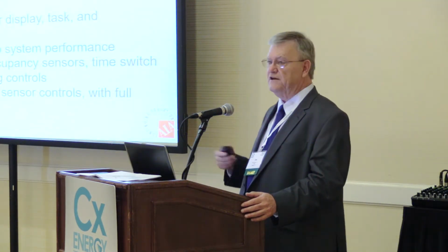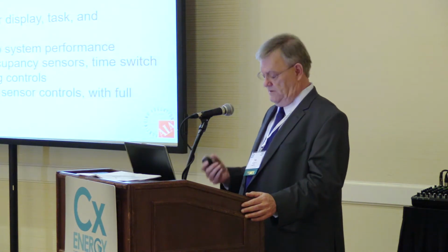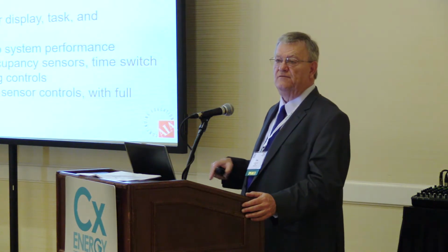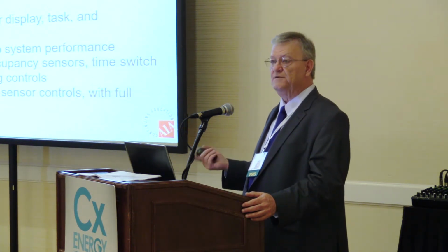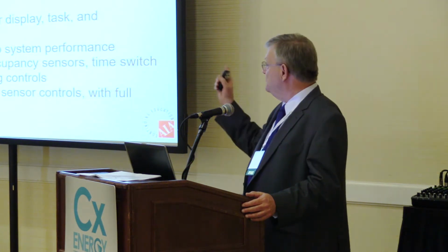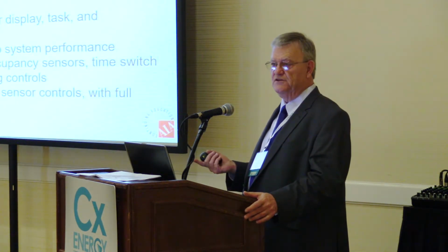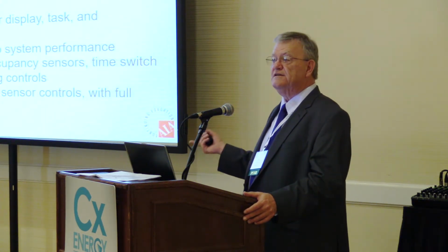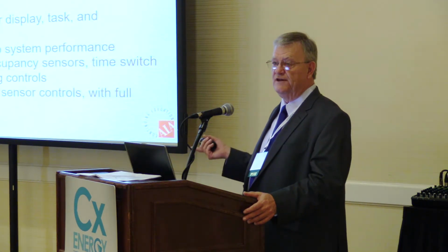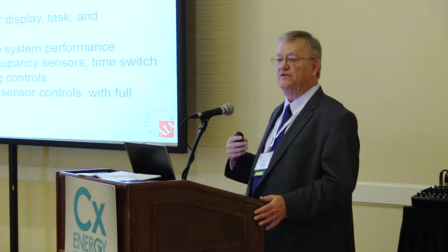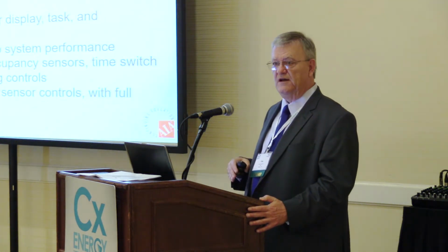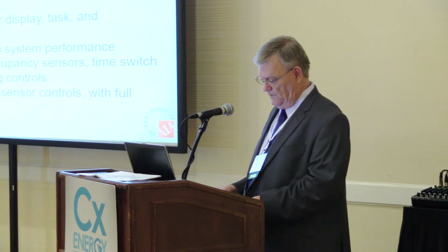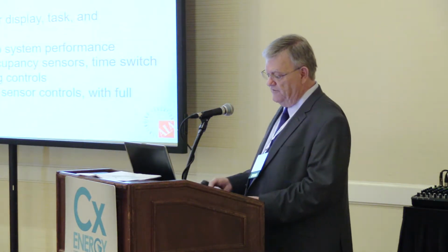We're not going to go any further. There is an ASHRAE 2016. It's out, but it hasn't yet been declared by the Secretary of Energy to be more efficient than the previous version, and that isn't scheduled to happen until about September of this year. IECC has that certification from the Secretary of Energy, and that's why we have seen a lot of activity about it now. When the Secretary of Energy makes that declaration, federal law requires various jurisdictions to either adopt the code, adopt one that they claim is better, more efficient, or tell the reason why. So this is how they've evolved over time.